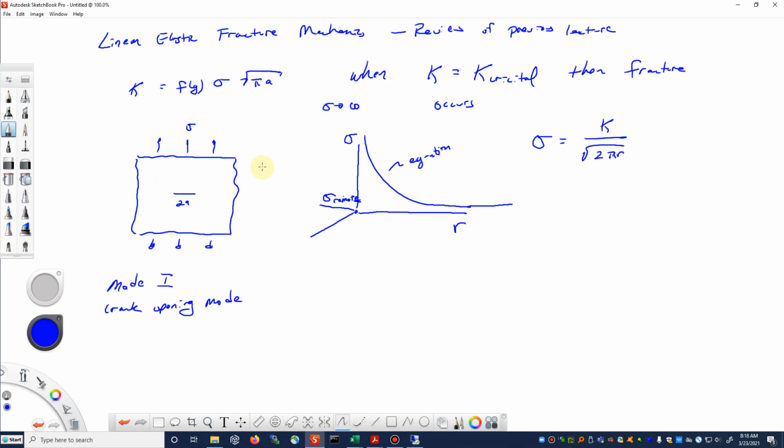Well, in our class, where we're primarily looking at metal fatigue, metals behave a little bit differently. They will tend to yield instead of fracturing without stop. Okay. So ahead of the crack tip, we may have a little bit of a yield zone where the stress is effectively flat for a little while, and then it comes down and rejoins this shape of curve.